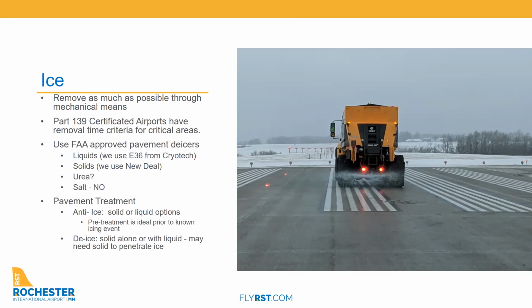So be aware of that. And then of course, no salt at all on an airport, inside the fence. We don't even drive trucks that have salt and sand anywhere near the airfield. We don't cut across, we don't drive the perimeter road, we don't do anything. So we're really careful to make sure that we don't inadvertently drop a little sand somewhere, even if it dropped out of the back of the truck.